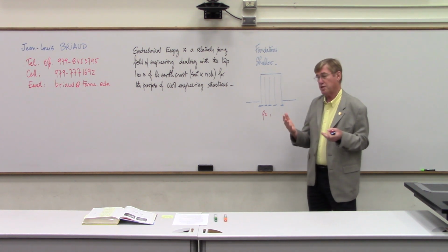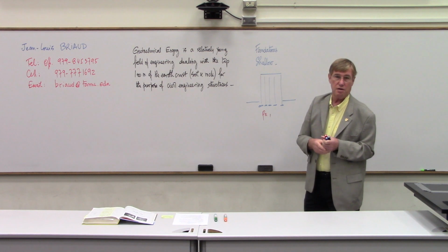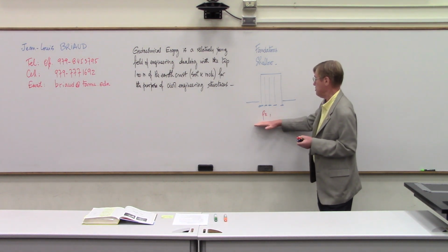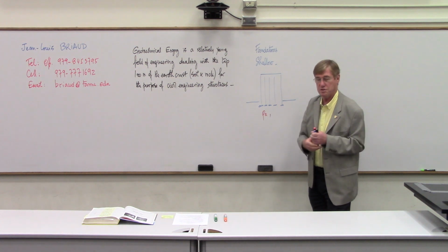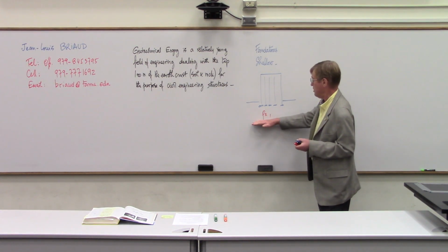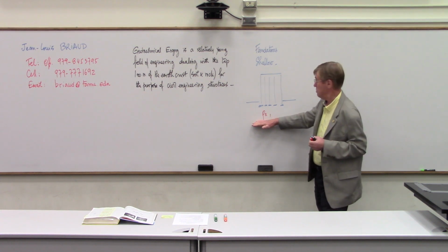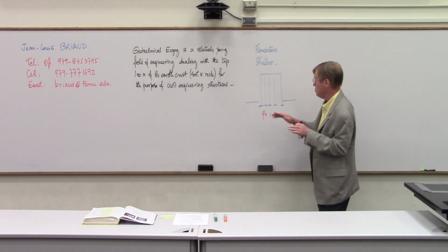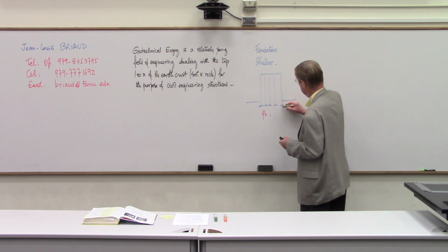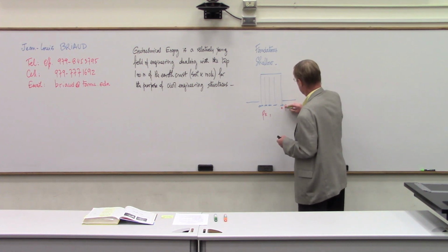Typically 2 or 3 are typical factors that we apply. Now we're going to load and resistance factor design, so it's a different story, but we have the ultimate pressure, we divide by a certain factor of safety to make sure we have a safe pressure under the footing here, safe pressure, P safe.